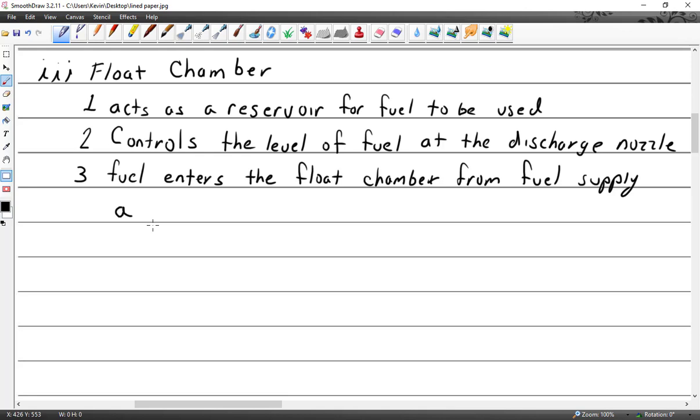All right, so if it is a high wing, or it is an older aircraft like the Cub or the Aeronca Chief or something like that, it doesn't usually have a fuel pump if it's got a carburetor. So it just has gravity feed. Gravity feed systems are going to run about 3 to 5 PSI max if you can get it out of it.